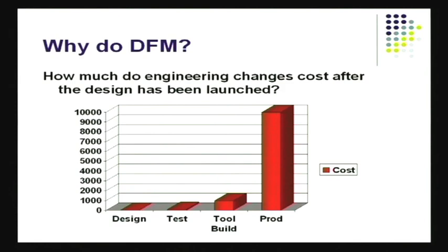Why do DFM? In fact, if you look at the engineering changes that are required many times after the design has been launched, which means after it has been commercialized, if I've not kept DFM in mind, if I've not kept this end step, which is manufacturing, in mind, and if I just do a design and throw it over the wall and it lands up in the manufacturing shop, there are going to be a lot of problems. If you look at engineering changes, many times a lot of things are discovered when you actually get into manufacturing. A lot of problems are discovered when you get into manufacturing. That's something we'd like to avoid, we'd like to minimize.